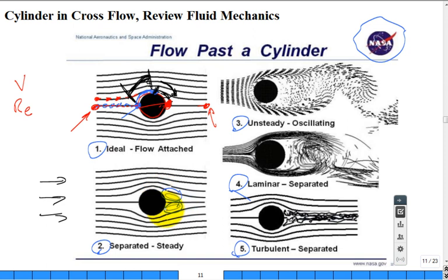A little recirculation region, and because of that unfavorable, adverse pressure gradient, there'll be a point up here where something happens, down here something happens, and the fluid will kind of go like that, but then you just get this trap, like going in a circle. That's a recirculation region on the backside. This is a point of separation, where the flow separates from the body. Oh, it was following it nicely in the front, but in the back, it wants to separate and form these little recirculation regions.